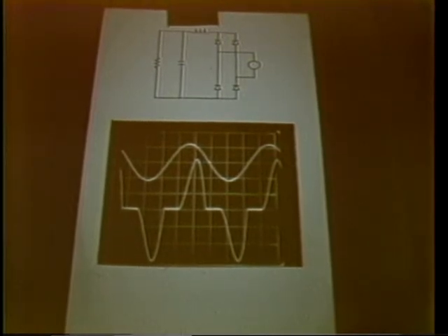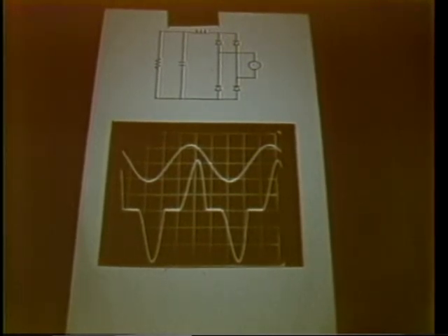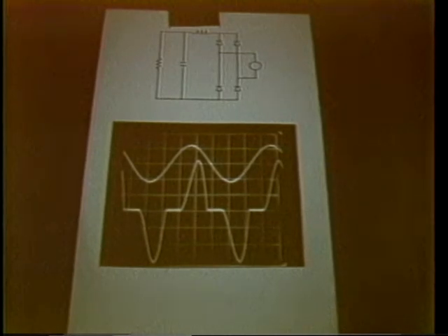The AC line current is rich in harmonics, has a high ratio of RMS to fundamental, and a poor power factor. Harmonics cause interference, and a poor power factor loads the line unnecessarily. What you see here in the line current is typical of the line current in your TV or PC. In fact, what you see here is probably somewhat better. See the next slide, please.